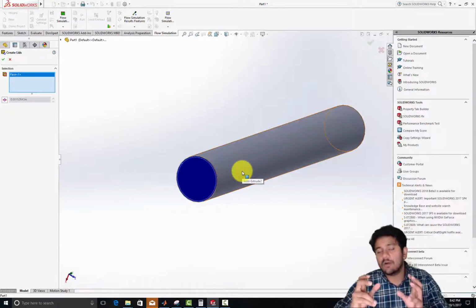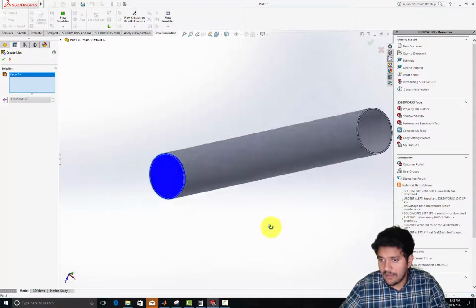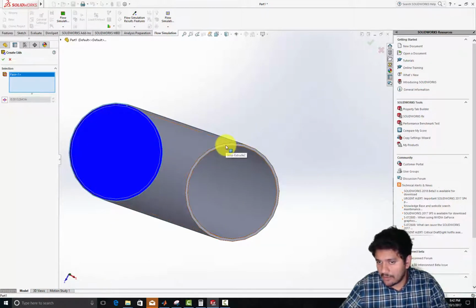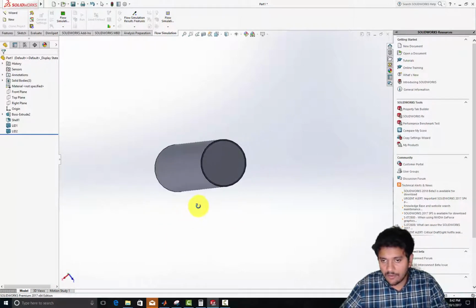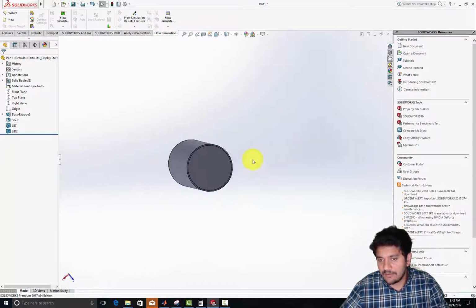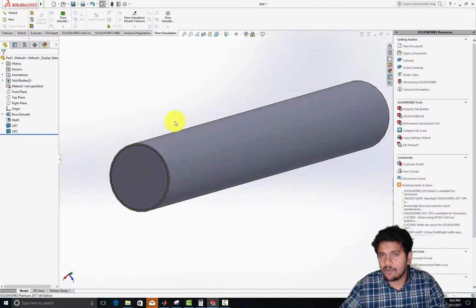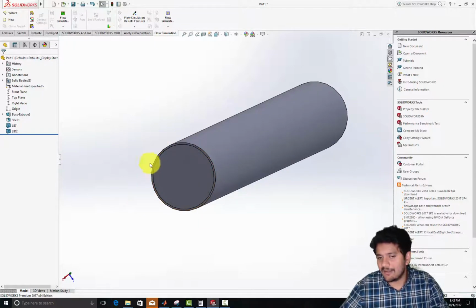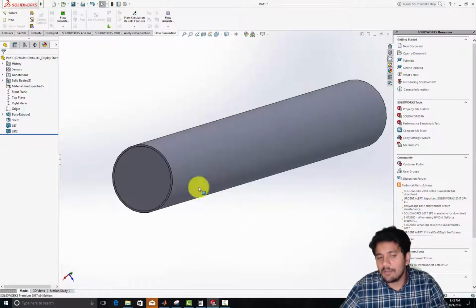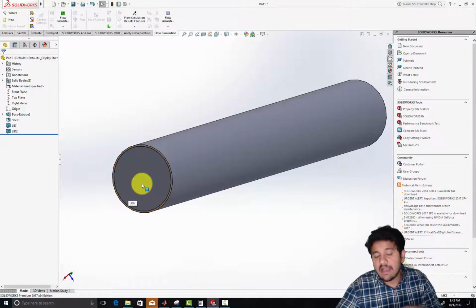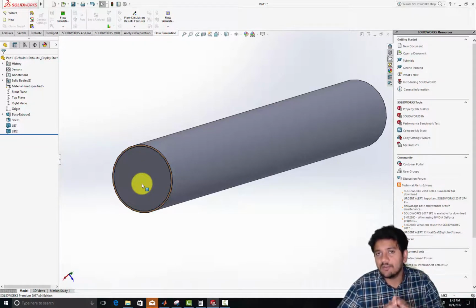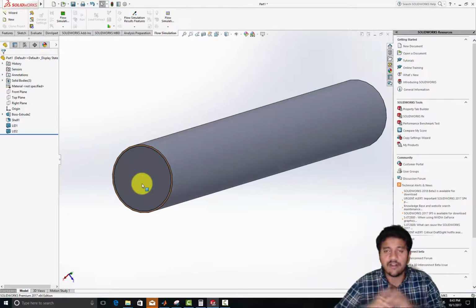You need a closed volume in order to create your mesh successfully. Similarly, I'm going to click on this face and these are going to be my two lids. When you rotate the geometry, you will see that these are closed. Now, if you know a little bit about CFD already, then this is like a non-manifold edge. If you don't understand what that is, don't worry about it. But basically, you need these lids to close the geometry. Different CFD codes have different practices, but the concept is you need a closed surface so that you can create the mesh either inside or outside the geometry.